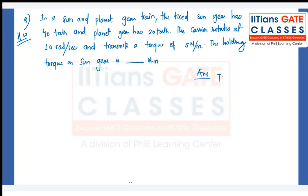The answer in this case is TS equal to minus 3.33 Newton meter. First of all, you calculate omega p. Because omega of the carrier is given and the sun gear is fixed, so omega p you can calculate. That you will get as 30 radian per second.